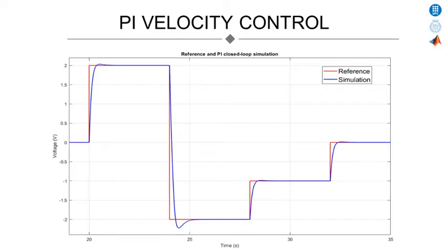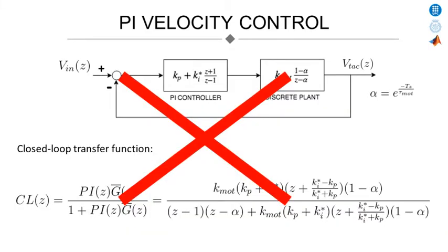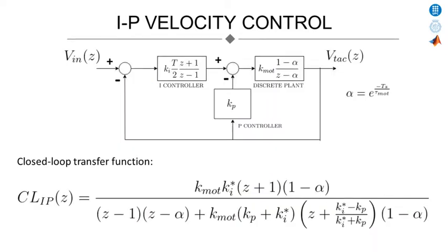We designed the PI controller such that we stabilize the plant in 0,8 seconds with no overshoot, but the obtained system didn't fulfill the specifications. So we will introduce another architecture when designing a PI controller in a first-order plant, as in this case, things get complicated because of the closed-loop 0. This figure shows another alternative manner to introduce the proportional and integral actions. This control structure takes the name of IP controller.